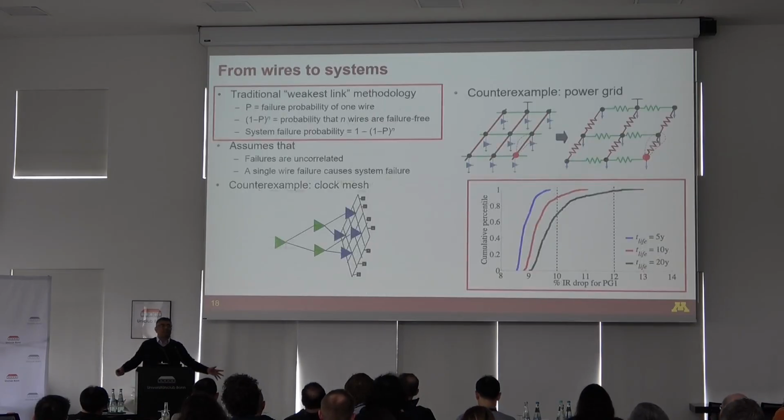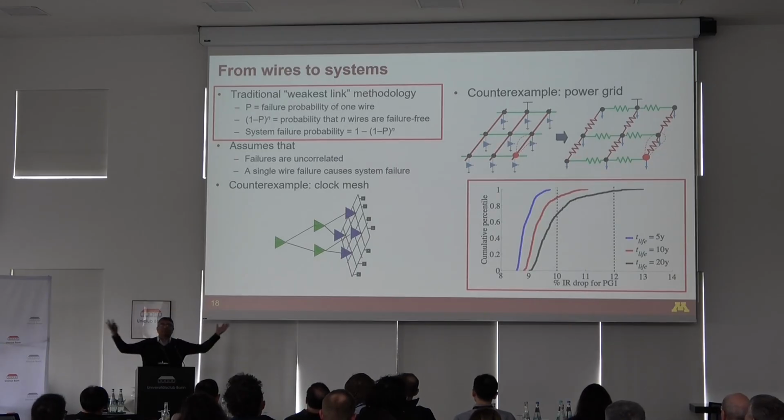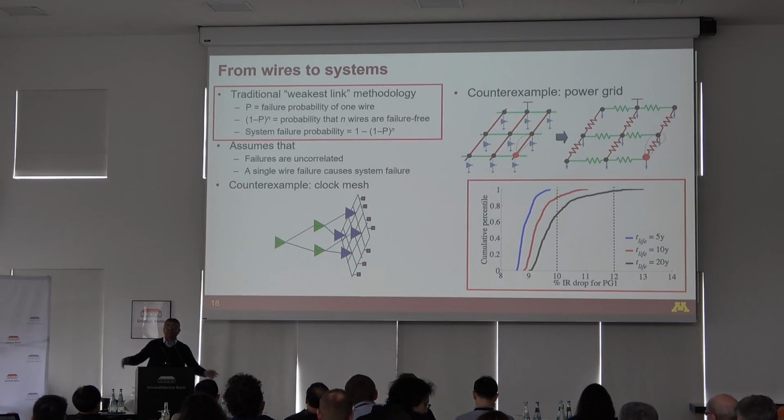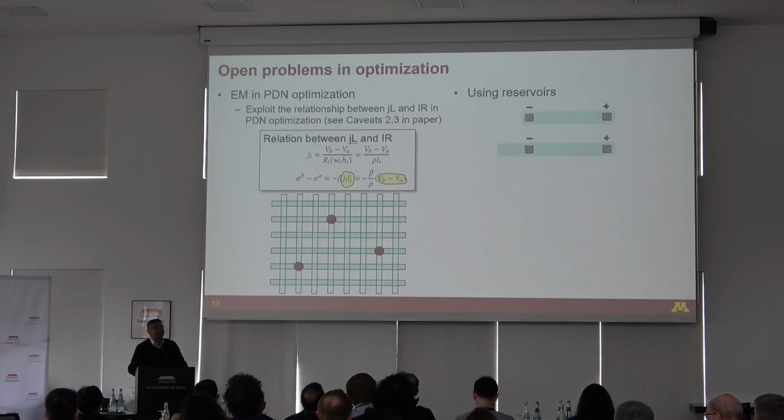The other way of thinking about this is, what's the solution? For both of them, if you have a high IR drop, widen your wire and reduce the resistance, or widen your wire and reduce the effective current density. So it's all consistent, and you can actually combine these things together.